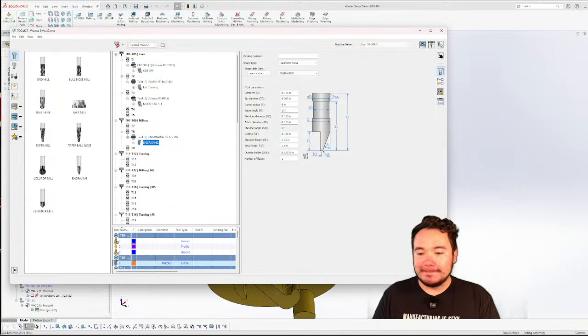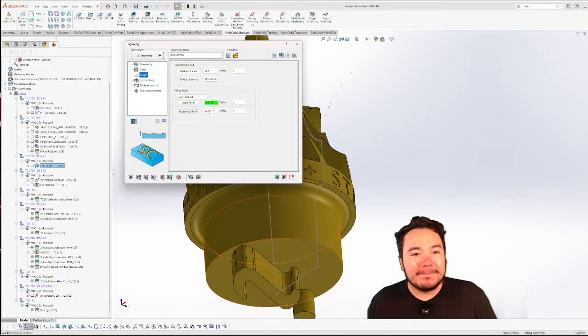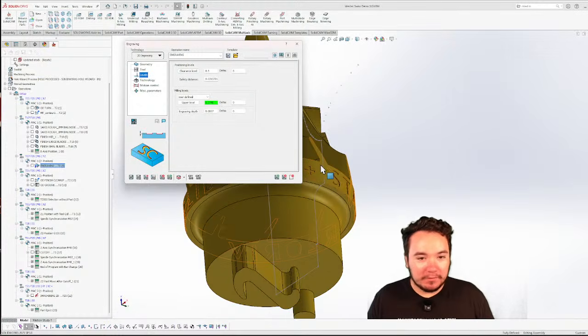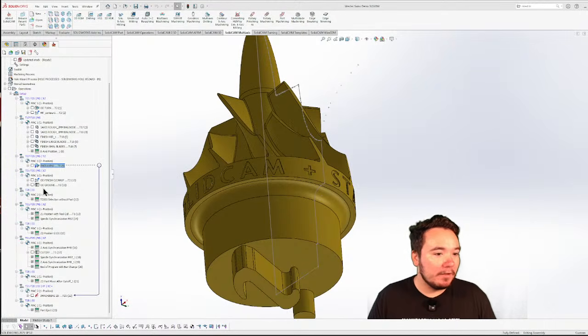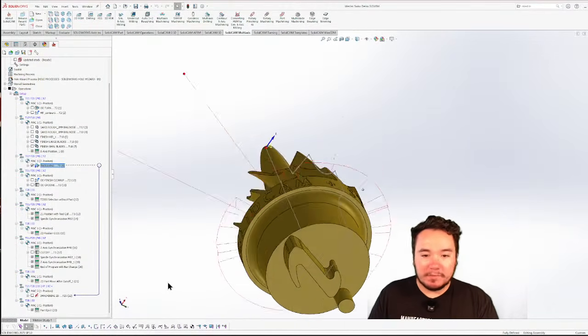Selected it. Chose my upper level, the OD of the part, and my depth for engraving, 6 thou, 7/10, almost 7 thou. Seemed to turn out pretty good on the part. You can see that toolpath there. Pretty basic toolpath.